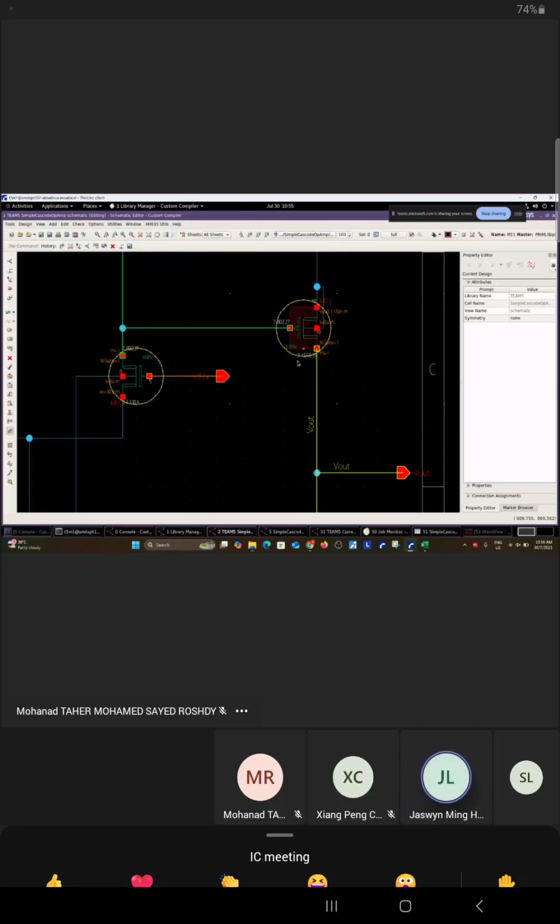Same width, right? Yeah, so 7.8. Wow, your VGS is very, oh no, VSG, right? VSG here is about 2.2. Then the VDS is very high. This is very low actually. Why is it so high? Let me think.